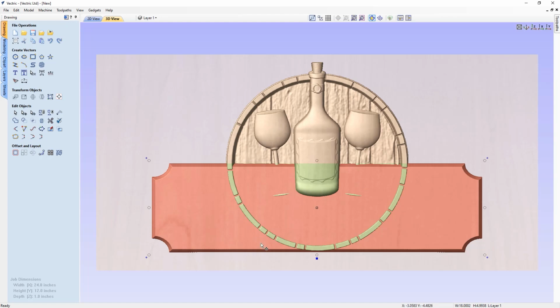And again, we know how to do that, but I'm going to show you a slightly different way to get to your component properties. With a component selected, with the transform handle showing, you'll notice that there will be a solid square. You can just go ahead and click on that, and that will bring up your floating properties dialog box.